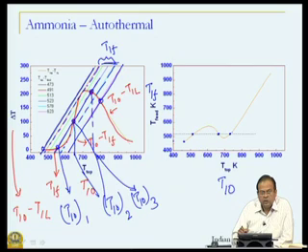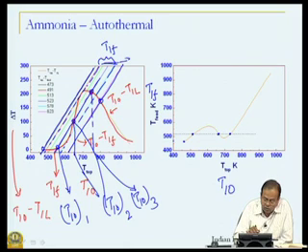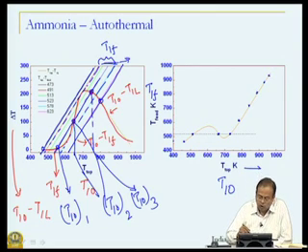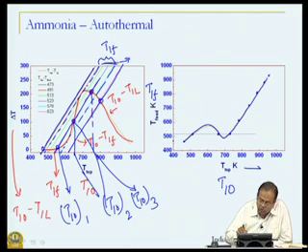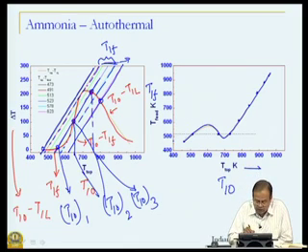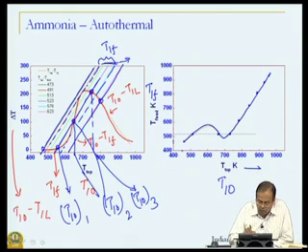That is 3 different possibilities of top temperature, and for any T1f greater than this value, that is on this side, we once again have a single temperature. So, if you join all this, you will get a plot which looks something like this. So, once again illustrating the fact that for low value of feed temperature, the top temperature will also be low, right, very little reaction.